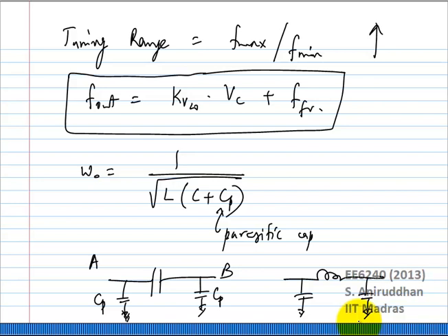If you take the capacitance, of course you know cases where the capacitance is a function of the DC voltage. Classic example is what? A reverse bias PN junction. The depletion region width is a function of the voltage, and therefore the capacitance is a function of the voltage.